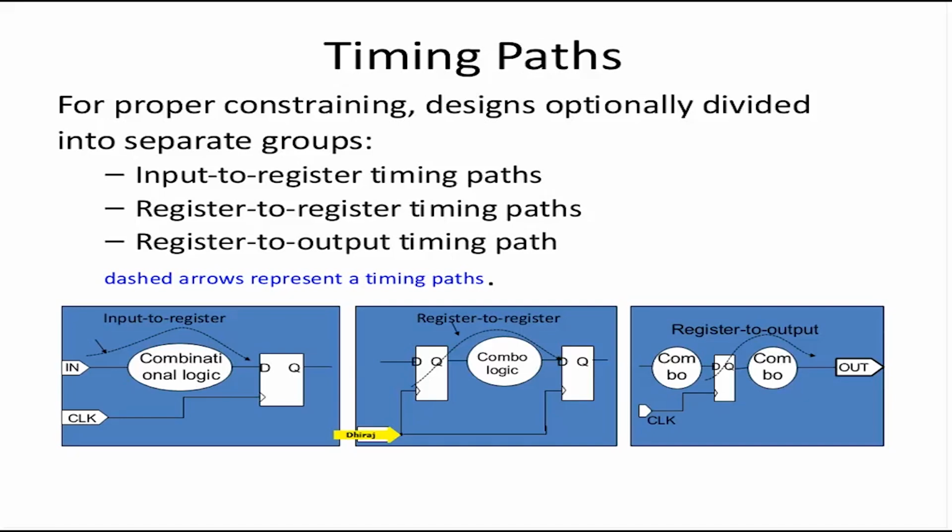DC knows the delay of this clock from the library. It knows the delay. DC will know the delay of this combinational logic. So DC knows all the cell delays, whatever is there in your design. Obviously, the cells will only come after optimization. But assume that you did not provide anything apart from the design environment, libraries, and RTL. We did not define any optimization constraint and went through the synthesis.